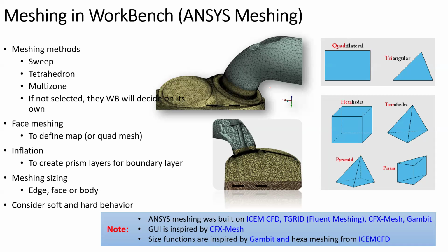And why did we do this? Because if you go through the meshing side, these meshing techniques will be the same for every problem. The only difference would be that every problem will require different specifications of the cell size, the method, and the inflation layers. But overall, the method will remain the same. These options will remain the same for all cases, but their usage will be different.